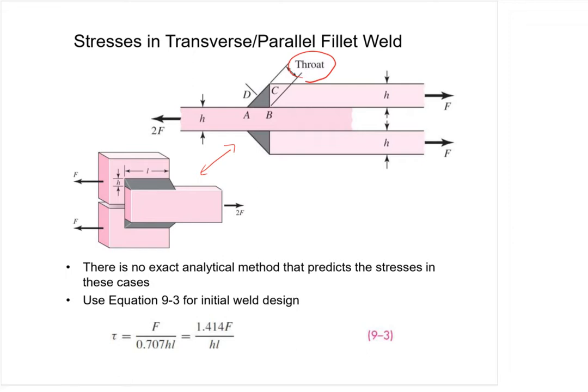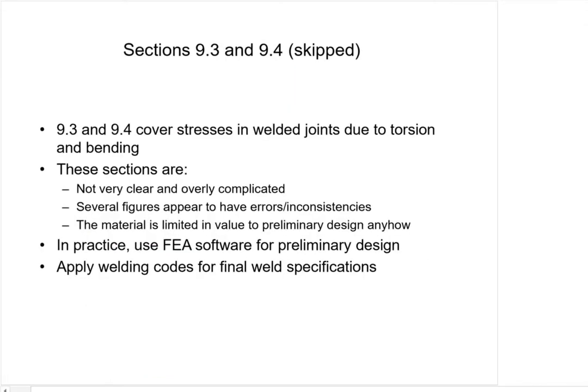And if you have separating forces in this case, we're looking at shear stresses, not tensile stresses. And you would use this formula for these two welds to determine the shear stresses that are acting on these transverse or parallel fillet welds. And that's pretty much it for the stresses.